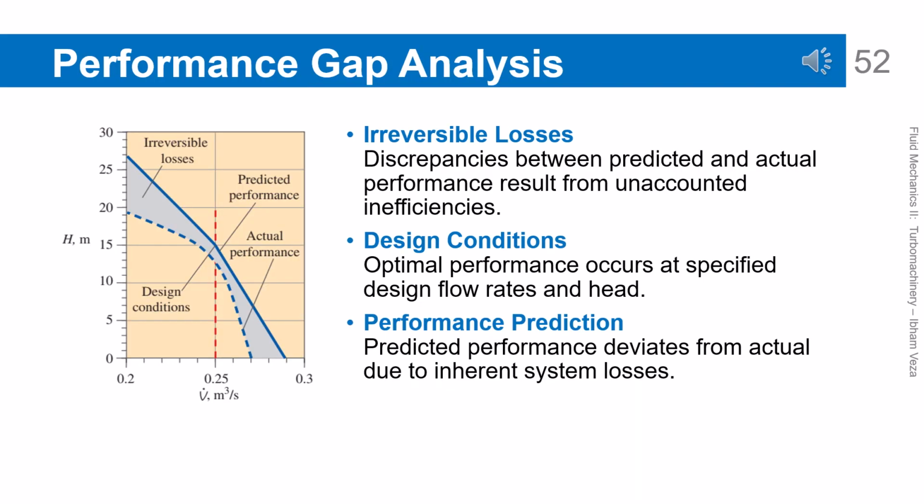Performance gap analysis. The difference between theoretical and actual performance is mainly caused by irreversible losses. Pump designs are usually optimized at a specific operating condition called the design point. Outside this condition, the actual performance deviates from the prediction. Therefore, test curves are very important to represent real pump behavior. Understanding this gap is essential in real engineering applications.